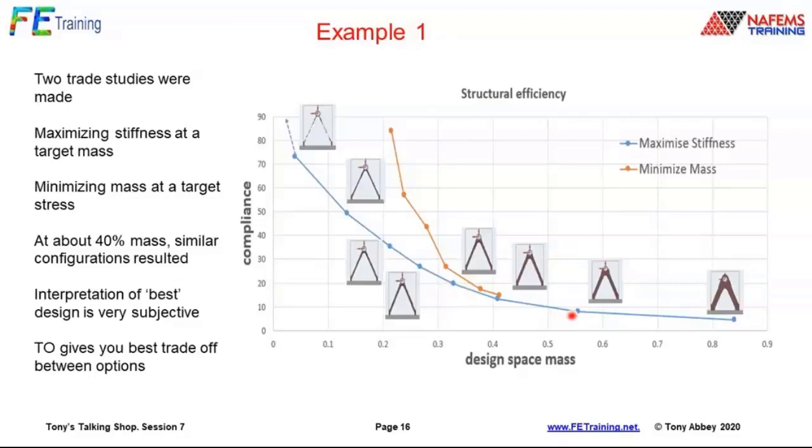So I'm always a little bit concerned about generative designs which are producing thousands of designs. How do we actually come up with a strategy to say these are the ones we want? Well, with this Pareto curve, I'm going to make a decision. Do I want it to be heavy and stiff, or very light and very flexible? That's my decision as a designer. I can make my choice along here.